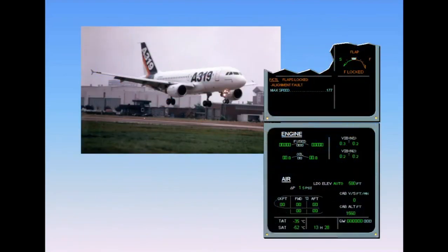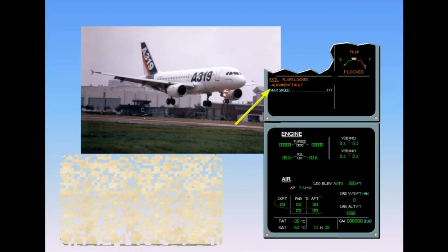The flaps are equipped with the flap disconnect detection system. This system will detect attachment failure and inhibits flap operation to limit further damage. In this case, you will get an alignment fault. The procedure is similar to the flaps lock procedure seen previously.